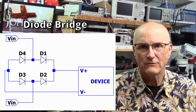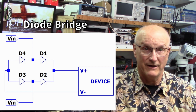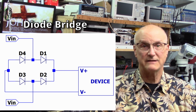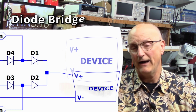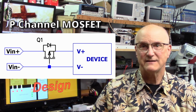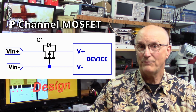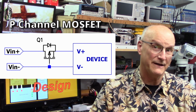I've also seen folks use a diode bridge so that the input, well, didn't care how you wired it. It just worked. These also experience the same voltage drop issue that this simple series diode exhibits, only twice over. Now, this is my favorite approach because it does not have as high of a voltage drop of either of the diode approaches. It uses a single P-channel MOSFET. So how do you design this in? How do you choose that device?